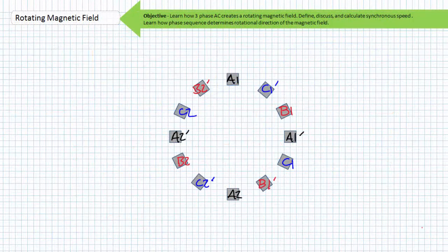If we were to examine the particulars of the rotating magnetic field internal to a two-pole pair per phase stator, we can move beyond our previous simplifications. One could also say that this is a four-pole per phase stator, or, since it's designed to run on three-phase AC, a 12-pole stator. This stator necessitates 6 windings, A1 and A2, B1 and B2, C1 and C2, 2 for each phase. Pole pairs are created from the opposite ends of a single winding wound around an iron core.